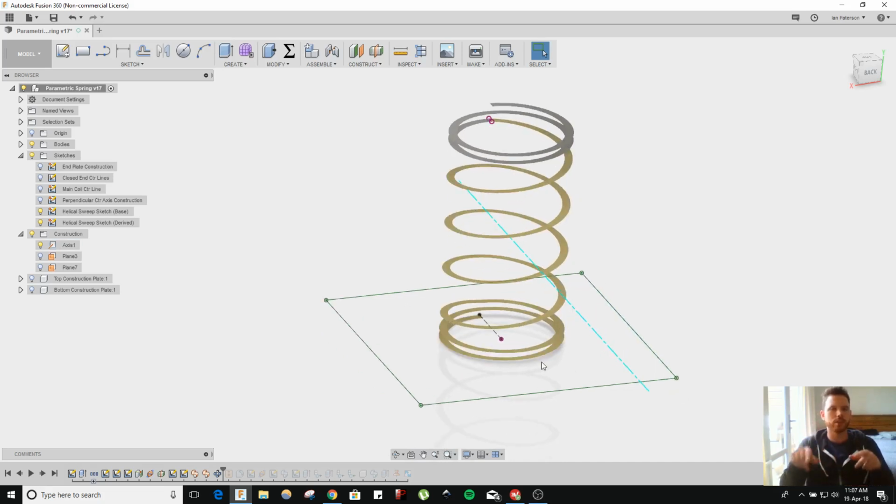But what actually stops you is that the move command in Fusion at the moment doesn't allow you to do either a 360 or a 0 degree rotation, and that makes sense because that isn't a move. But it means that if you put a formula into the move command, with a rotation amount somewhere between 0 and 360 degrees, and you happen to land on one of those values, it will error out your move command.